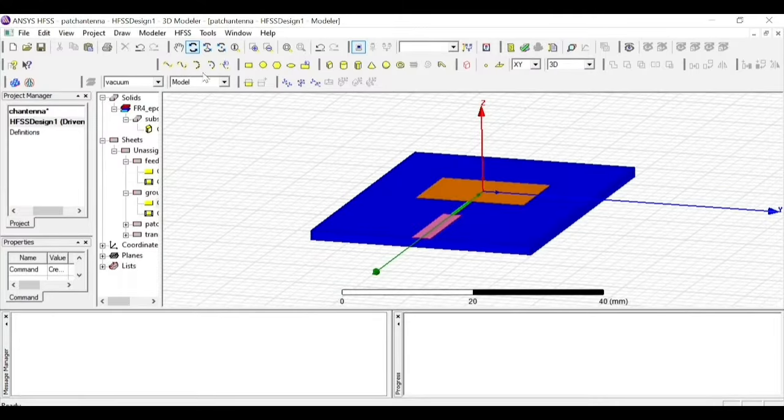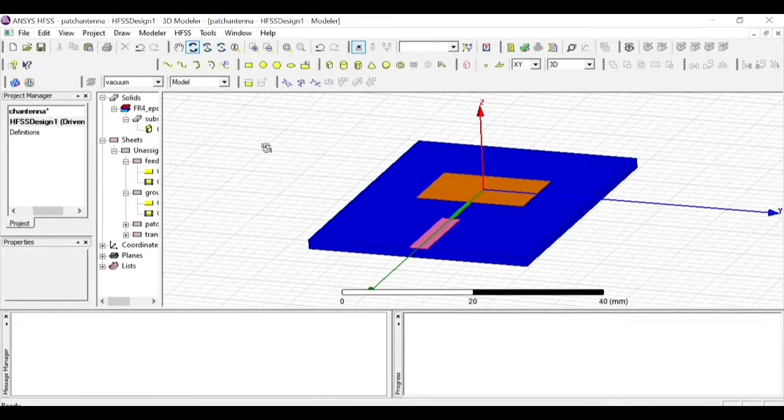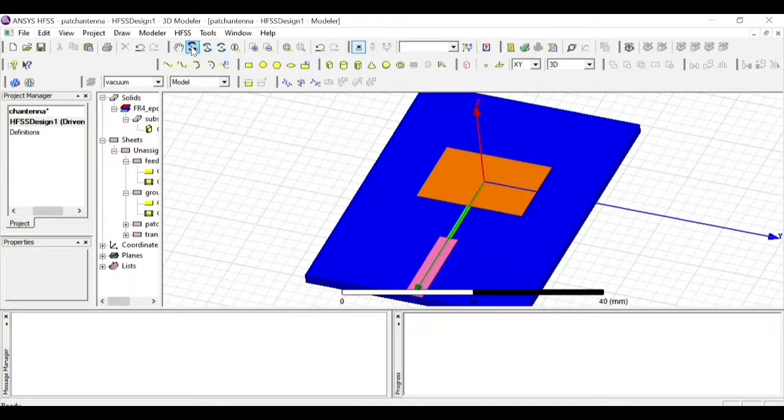Next, you can say, Yashwardhan, you have created the antenna and the model, now what should I do next? Next, let us go to give various excitations to the design. Before we do that, let me first unite. You can easily tell that my rectangular patch, my lambda by 4 transformer line, and also my feed point are separate figures, they are not united. If I give any excitation here, there will be a little bit of drop. To avoid this, first of all, let me unite this.